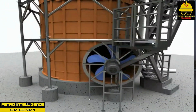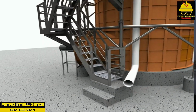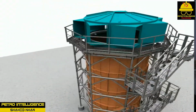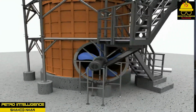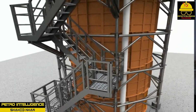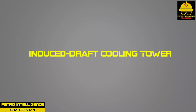Air in forced draft towers can have high velocities, but the exiting air slows so much that it is recirculated back into the tower, cutting efficiency by 20%. Forced draft cooling towers have much higher heat transfer rates than atmospheric and natural draft cooling towers, and they are significantly lower in height. This type of cooling tower is less efficient than induced draft towers because some hot air is recirculated.